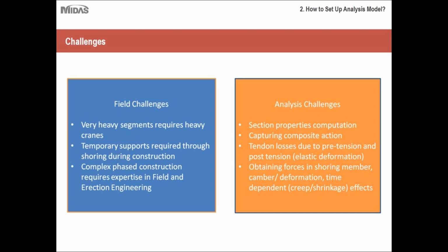Then you always require temporary supports, and for this you require shoring during the construction work. Then since their construction is pretty complex, they require complex phased construction, for which you really need to have expertise in this field and erection engineering. So not everyone can just start working on this type of project.